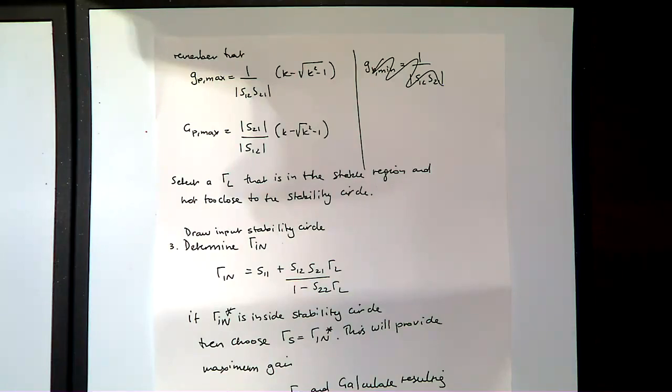So last time we chose it because we wanted maximum stability, so we chose it so that it had the maximum real part. Or you can choose it so that it's in a stable region, but also closest to the origin, so that I've got the smallest standing wave ratio at the input. But that may also present some challenges, and we'll talk about that in our example.